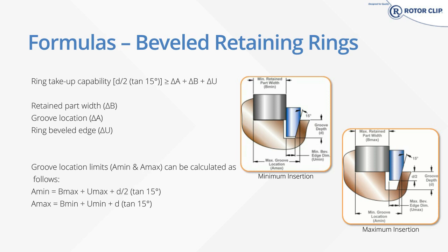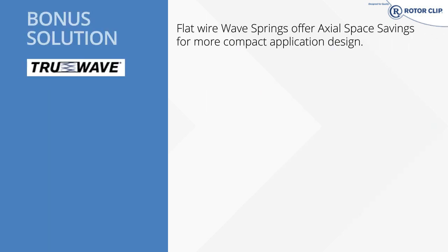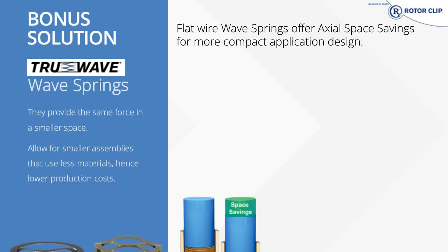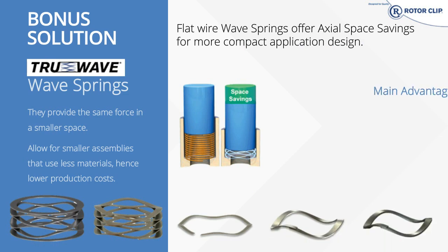So if you're trying to make a smaller application, trying to get less head space, wave springs may be the way to go. Likewise, if you're using Belleville washers or a Belleville stack, switching to a wave spring gives you a single spring option. In a situation where you have 4 Bellevilles, you can replace them with one wave spring. You don't have to worry about quality complaints and possible rebuilds if the assembly line only installs 3 Bellevilles instead of 4.